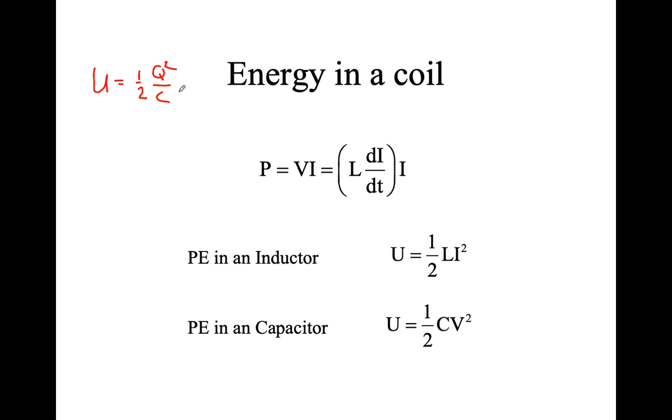It seems to me that an inductor is storing energy as well in that magnetic field, okay? But it's storing energy as a current and the magnetic field that the current creates. And so unfortunately, I can't talk about a fixed amount of energy like I can in a capacitor. You can charge up a capacitor, disconnect it from the circuit. As long as it still maintains that charge, it's like a little battery almost that has that charge ready to dissipate when you hook it back up. You take an inductor out of a circuit and it no longer has current running through it, instantly the magnetic field goes away. You can't maintain it that way.